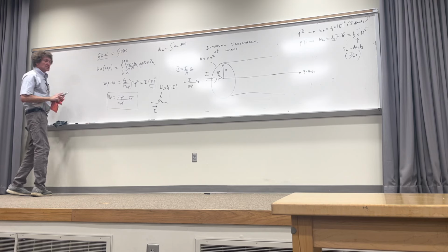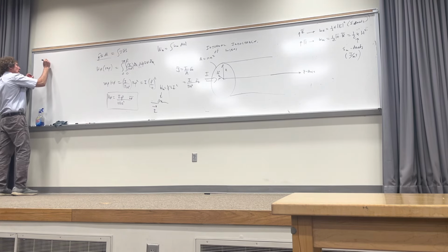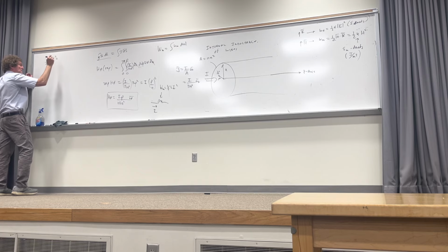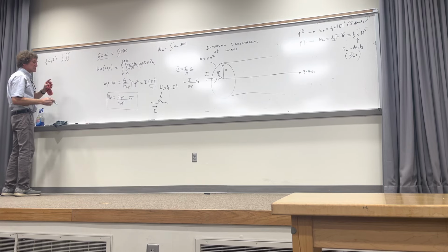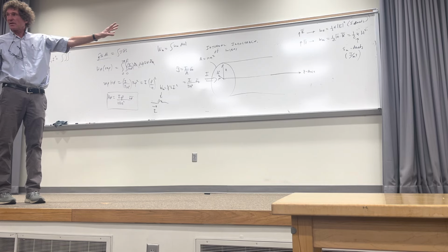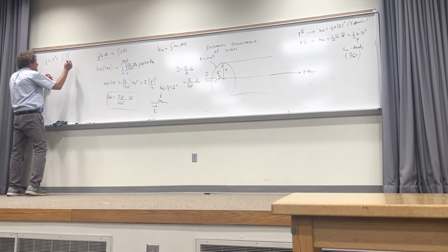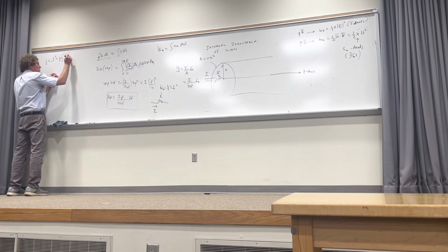So I want the energy density, and I'm going to say 1/2 L, and this will be internal, I'll put it L sub i, the internal inductance, times I squared is going to be equal to the integral. It'll be a triple integral because it's volumetric, of the energy density. Energy density is 1/2 mu H squared. You all see that over there? Make sure you know this for Friday. That's the energy density, 1/2 mu H squared. So here, I'll take the 1/2 and mu out in front, and it's H squared.